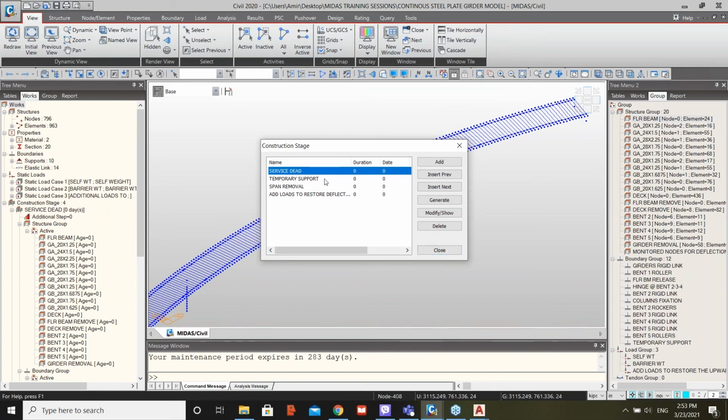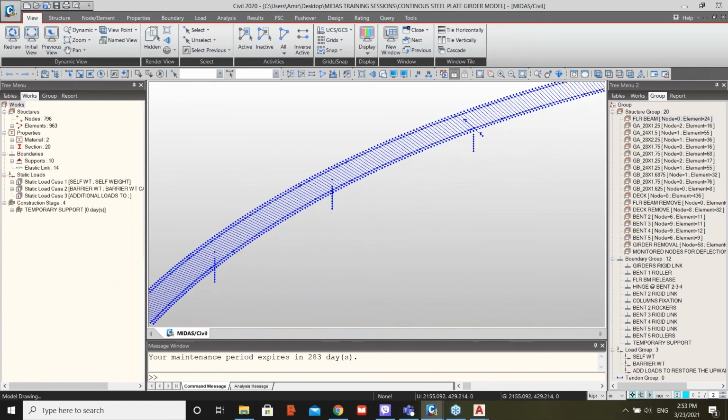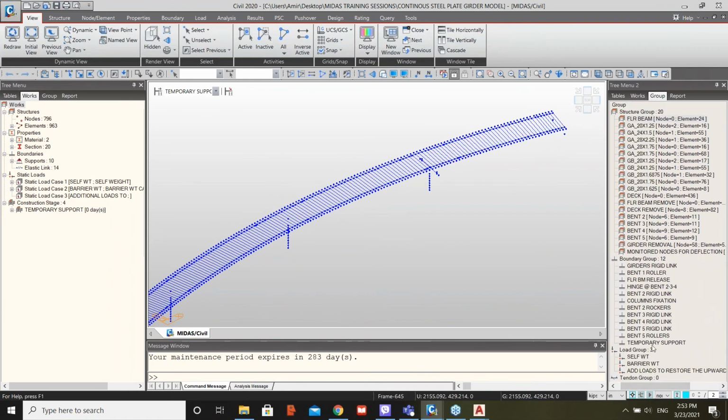And the repair scheme consisted of applying a temporary support first to the adjacent spans, at those particular selected locations. So you see the nodes that are highlighted here. This represents temporary shoring towers that were installed underneath the bridge at those particular points, because later, in the coming stage, when we start demolition of the deck, taking out the floor beams and removing the girders, this is expected to transform the system of the bridge from a full span to 2 cantilevers, one extending from this side and the other from that side.